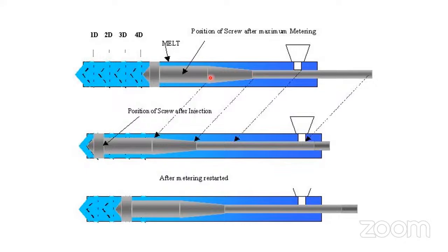Then compression zone will push the liquid melt into the metering zone. And the work of metering zone is to inject the material or to pass the material at the injection stroke as per the size of the mold. The metering zone will meter in only as much melt as the mold needs. I told you 70 ml, 50 ml, like that. Depends upon the material.